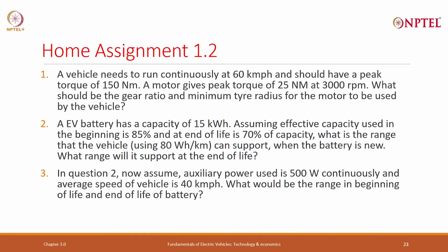Yesterday, we used a dynamometer to convert the petrol moving engine to hydraulics, and then the petrol engine drive itself using the dynamometer could produce electricity which could charge an auxiliary battery. For an electric vehicle, I just use the main battery and use a DC-DC converter. This is the vehicle auxiliary.